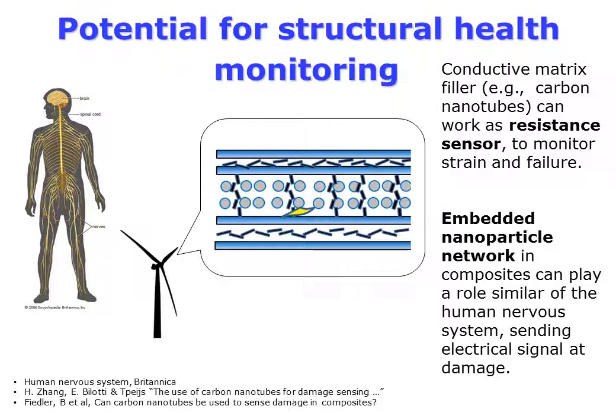Nanoparticles can build conductive networks, layers or fibers, creating the conductivity path in the material. The electrical resistance of the materials with nanoparticles is changed under deformation and failure, due to changing, eventually broken, contact between adjacent carbon nanoparticles. The tunneling resistance between two adjacent nanoparticles also changed, due to changed distance between them.